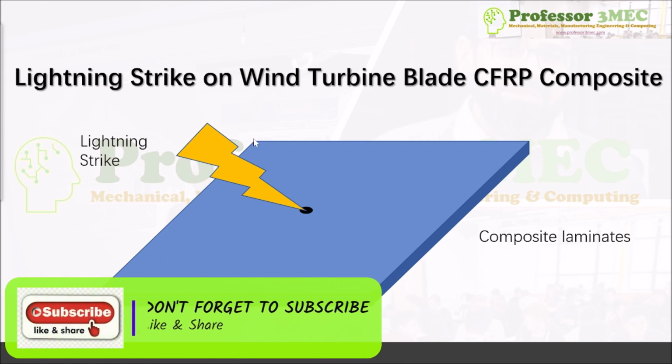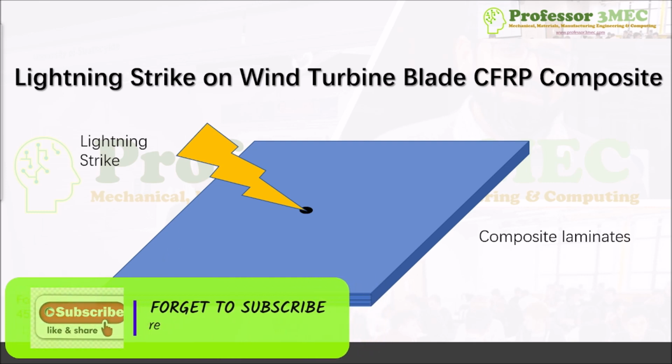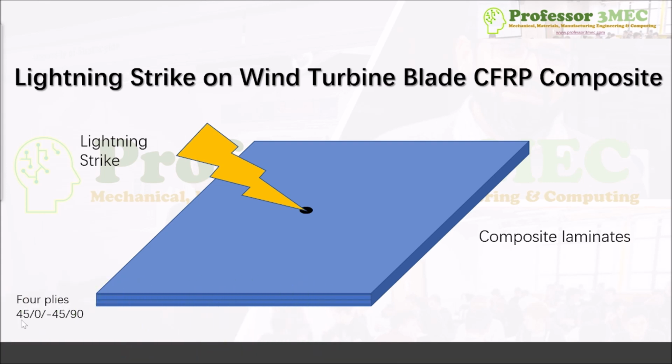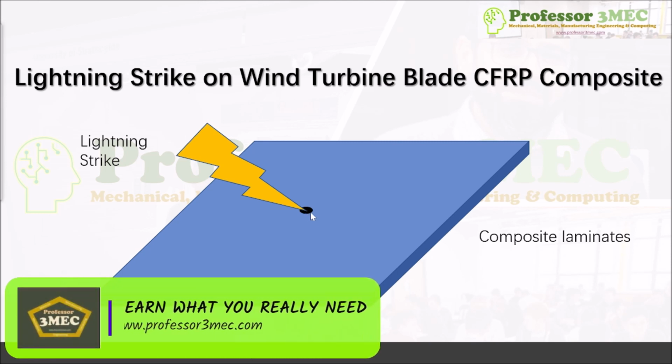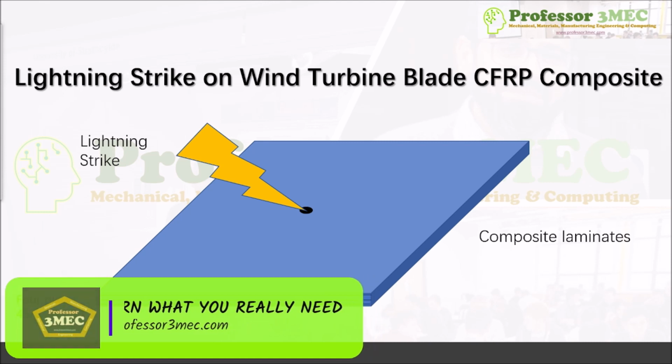So we will use a simple composite laminate, which is shown here. In this case, I'm going to use 4 plies, which will be oriented at 45 degrees, 0 degrees, minus 45 degrees, and 90 degrees. And lightning will strike somewhere in the middle of this laminate. And we will see how the composite really responds to this lightning strike.